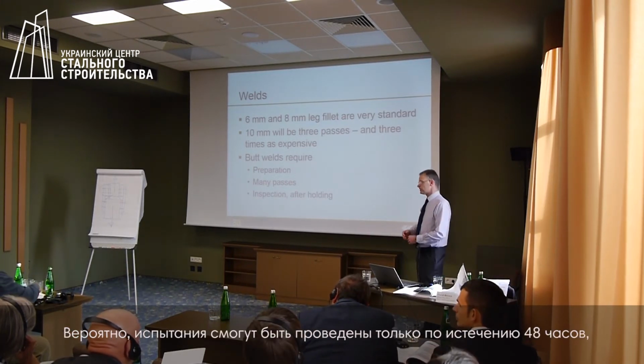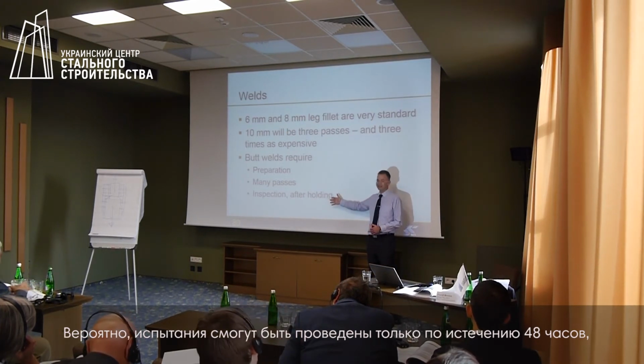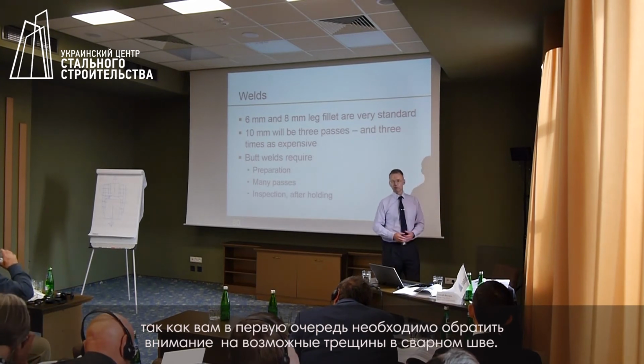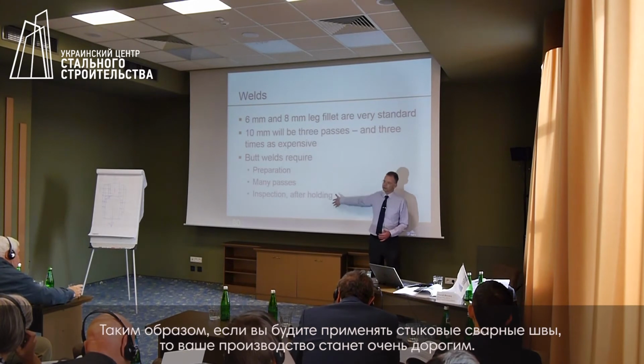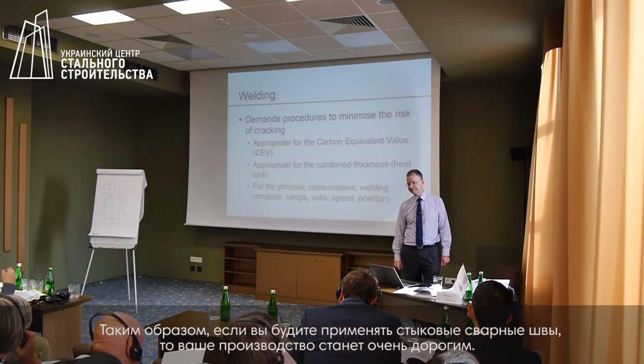Perhaps the testing will not be carried out until 48 hours later, because you are concerned about cracking of the weld. So as soon as you start to specify butt welds, fabrication starts to become expensive.